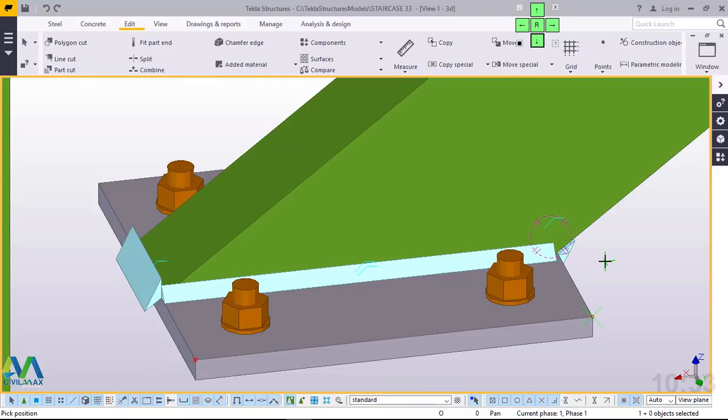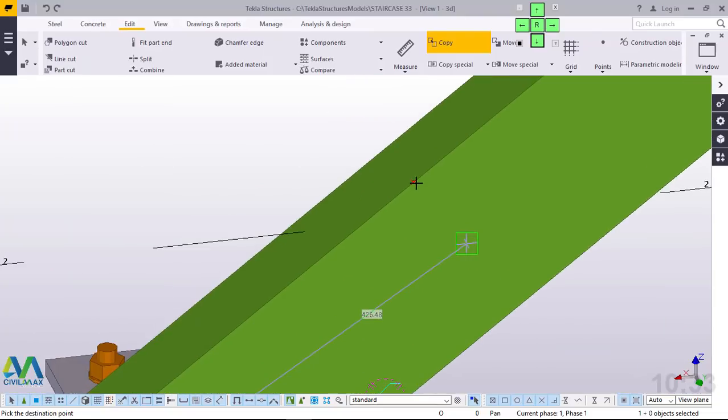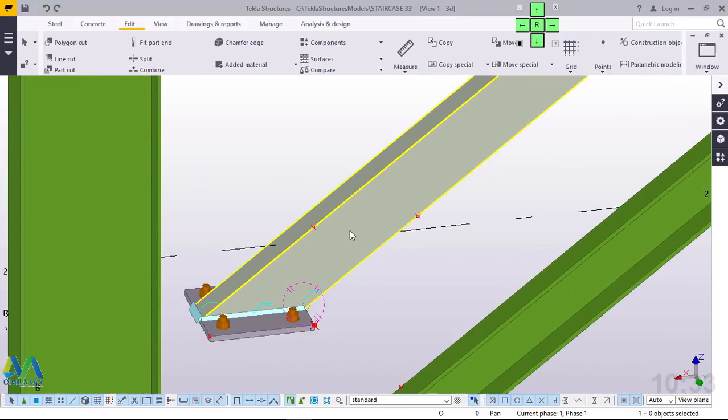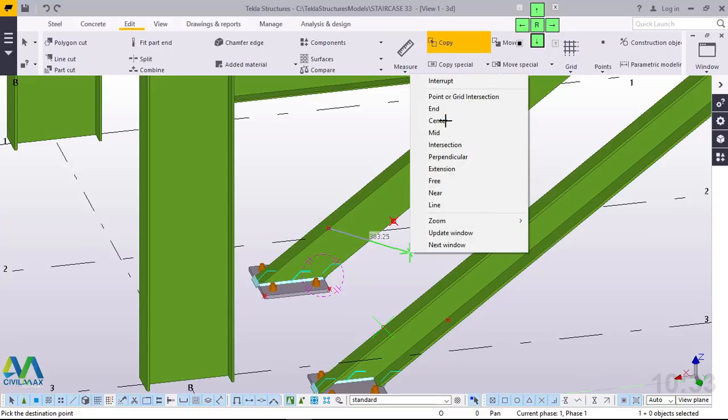Snap right there. Now I'll copy one of these points. I'll pick on this, then hold this point from this end, then check it to this spot. You can see the point is there, aligned properly. Then I want to transfer the same point here. I'll click on this, right click and come to copy and pick it from that spot, and I'll bring it to that spot. Right click and exit.